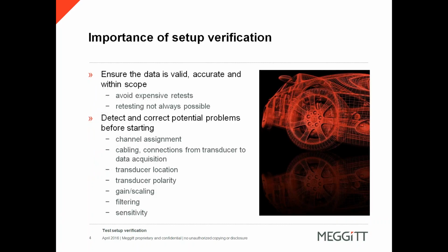Many tests require transducer setup verification to ensure the data is valid, accurate, and meets the scope of the test definition and objectives. Why? Well, such setup verification is needed to identify and correct potential problems before pressing the Go button on the test. If not, retesting might either be expensive or even not possible at all.